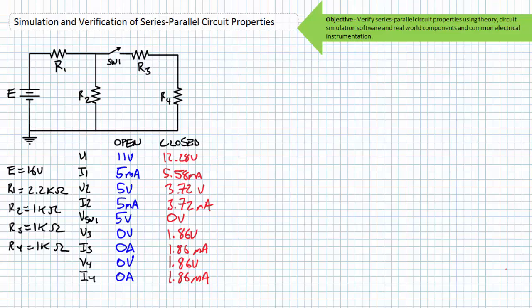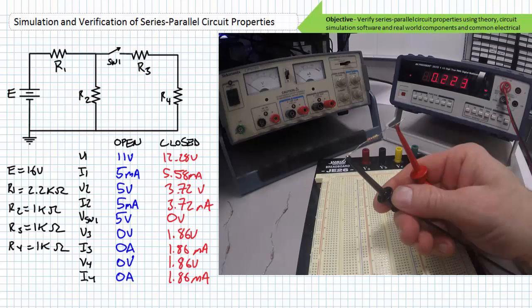For example, if you happen to pull a 220 ohm resistor from a component bin marked 2.2 kilo-ohms, your first clue of a problem will be the brown third band. If this escaped your notice, an ohm meter indicates this resistor has a value of 0.22 kilo-ohms, or 220 ohms, clearly not the 2.2 kilo-ohm or 2200 ohm resistance you're looking for. Again, your understanding of engineering prefixes is a core skill and will be continually employed.